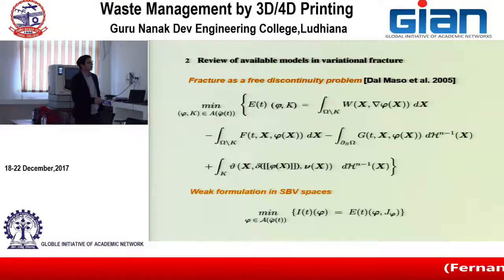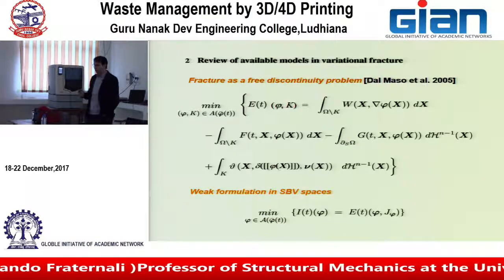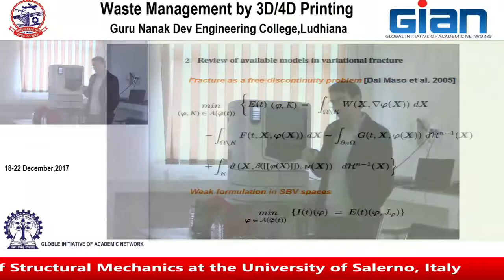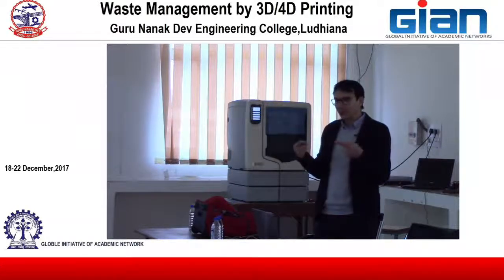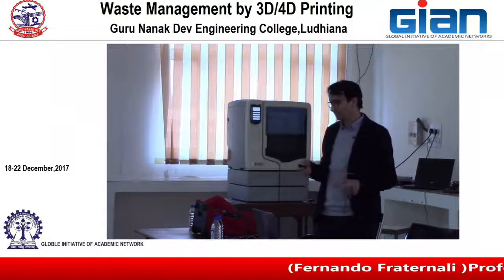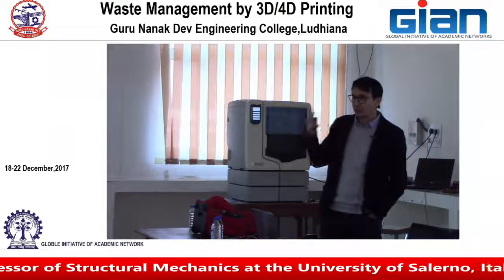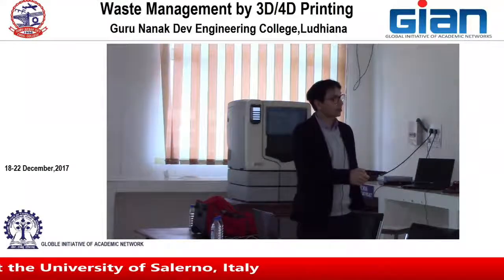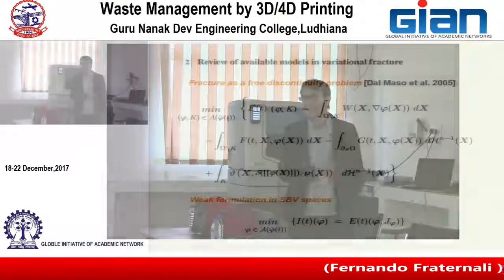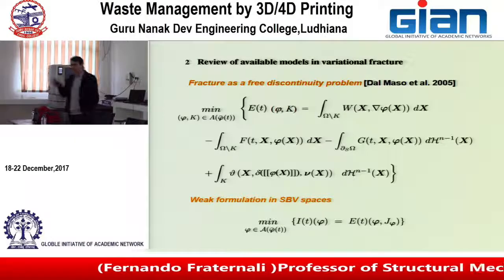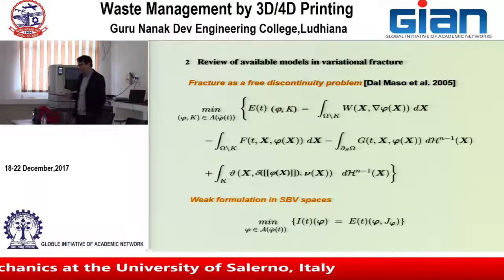In free discontinuity problems, the energy is a function also of the discontinuity set, because the displacement allows for discontinuities, which are basically due to the opening of cracks. And so the energy depends on two fields: the deformation map phi, or the displacement u, and K. K is the crack pattern in our case. It's the set of the discontinuities of the deformation map or the displacement field.